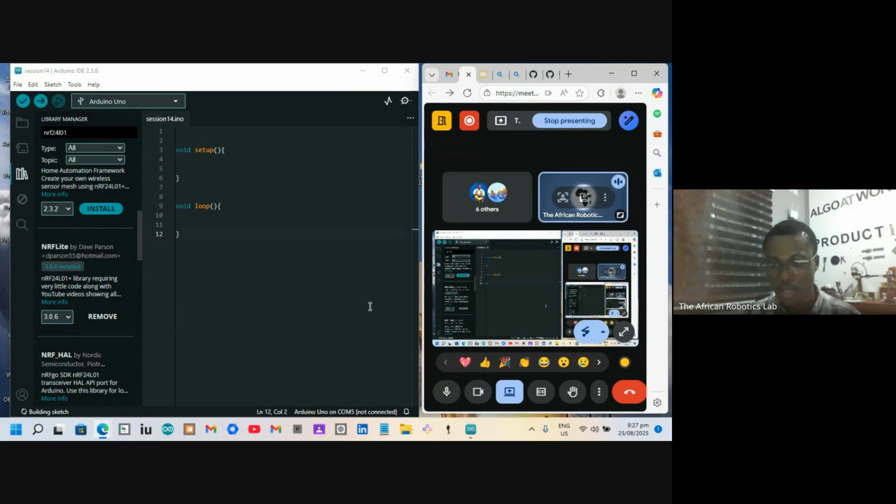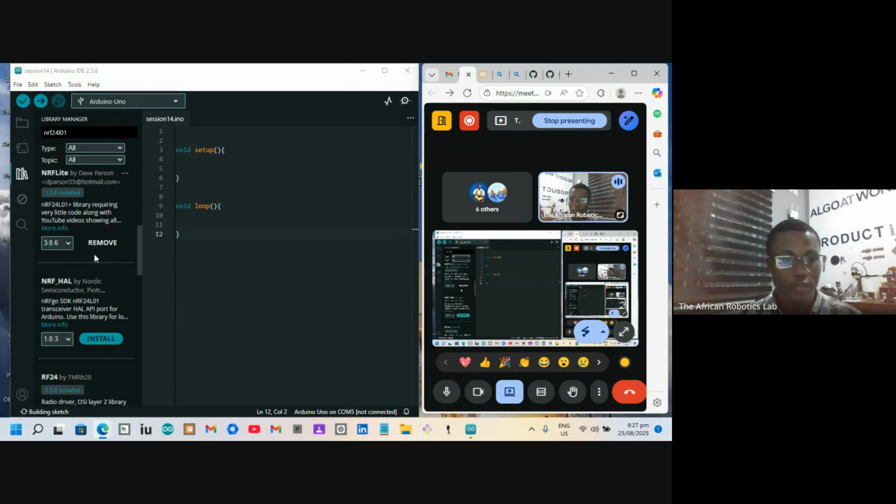All right, I think we are back. Thank you. So if you're working with this particular wireless module, you need to install a library. You just come in here and pick the library that you prefer. There's another library here, NRF HAL by Nordic Semiconductor. The one I used for my project was made by someone called Dave Parson, NRF Lite by Dave Parson.